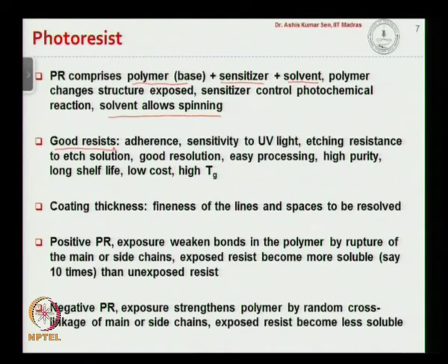A good photoresist will stick very well to the wafer, so it would have very good adherence, and it would be sensitive to UV light. Depending on whether it is negative or positive, accordingly it will cross link, or the links between the bonds are going to break. So it should react with the UV light, and the sensitivity to UV light needs to be good.